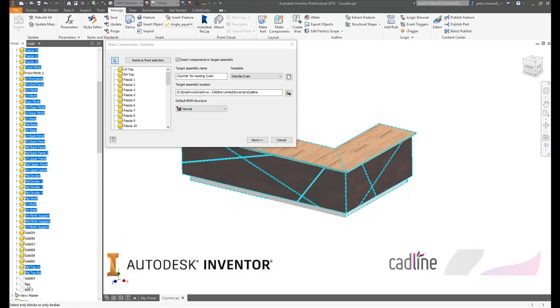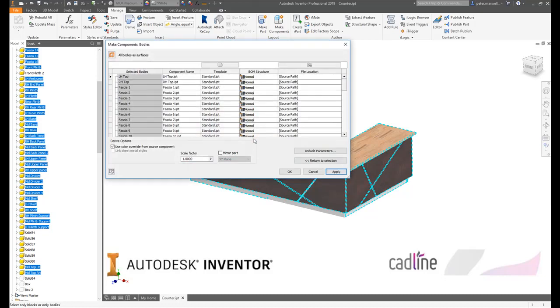Okay, I could take the box if I wanted, but I'm not going to in this case. So I'm going to hit next, and you'll see here it's got left hand top, right hand top, IPT. Okay, so these are now going to be individual part files. Because I've applied an appearance already, I can leave my use color override from the source component on. However, I could untick this, and then that would give me the ability to change the colors, textures, materials, etc.